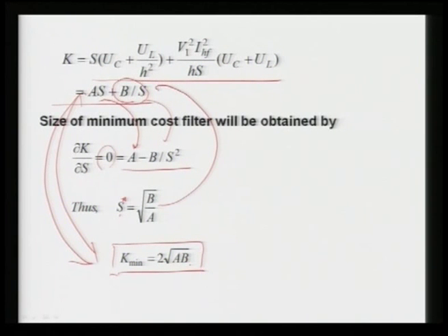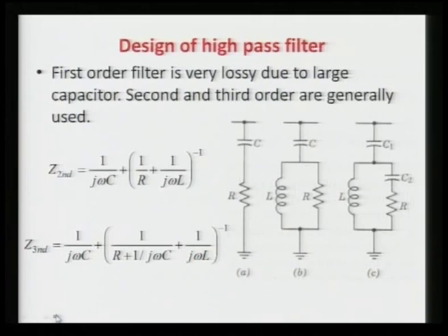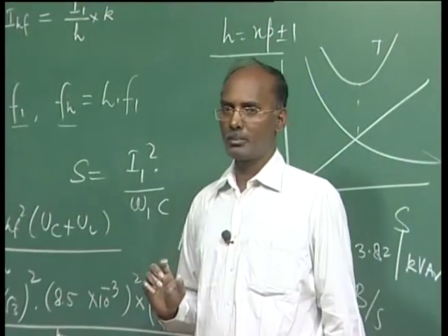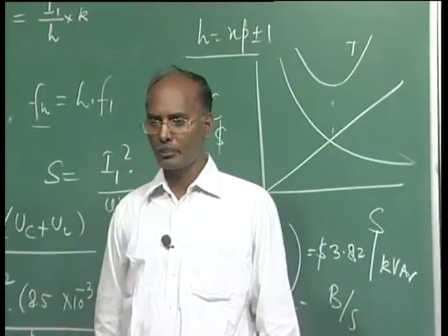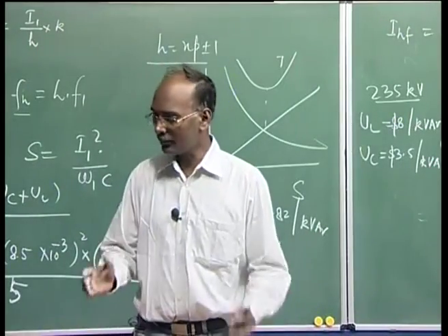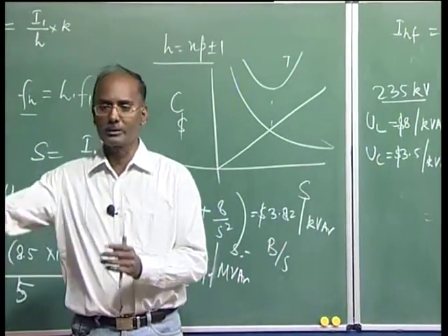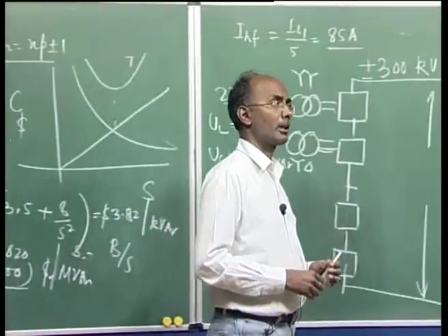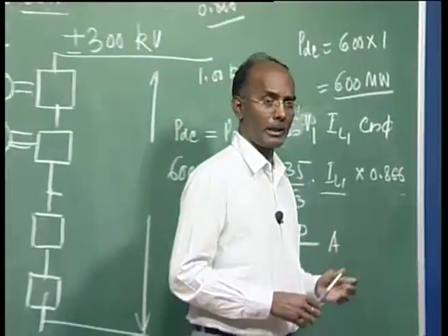Now, we have to go for the design of high pass filters. Till now we just saw your tuned filters, but for other harmonic components, if they are significant, we normally use band pass filters, so that the harmonics of a particular order onwards should not enter into the AC system. Whatever characteristic or uncharacteristic harmonics are there, we have to take care.